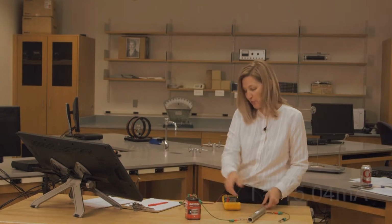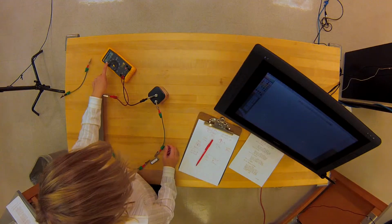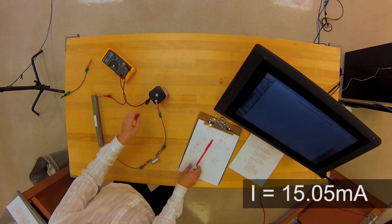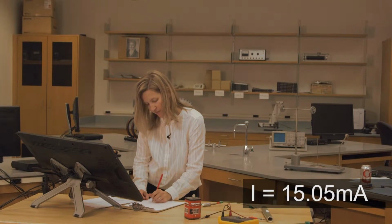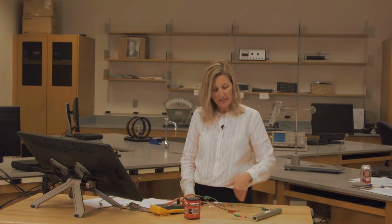Now I'll move it to after both resistors. When I place the ammeter after both resistors, it reads 15.05 milliamps. As you can see from our three readings, the current when resistors are connected in series is the same. So this is consistent with our observations from the water circuit. It's also consistent with the law of conservation of charge. So the charge didn't disappear and we didn't have charge created out of nowhere.